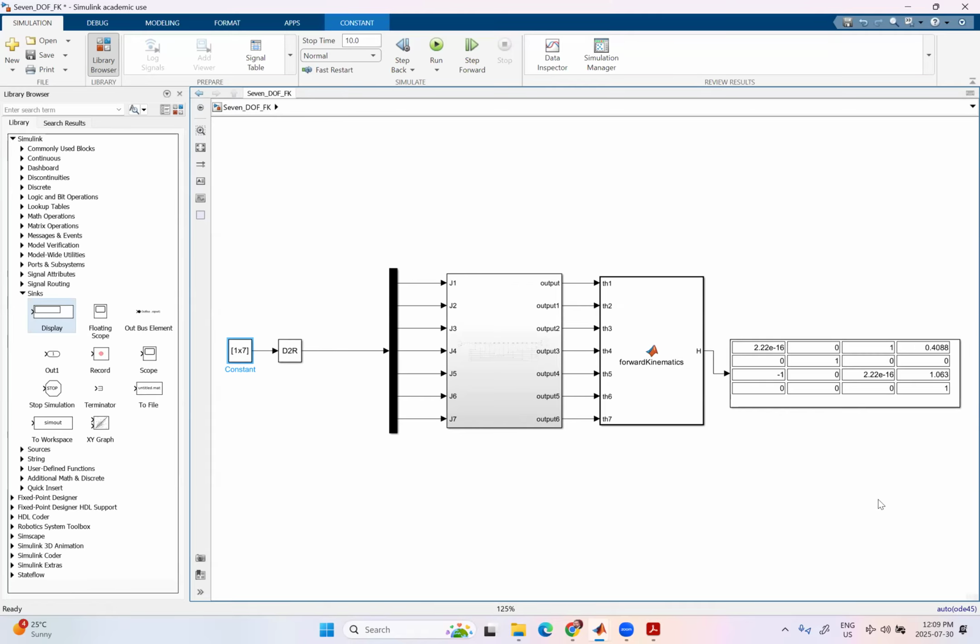And what are the next steps? Inverse kinematics, trajectory generation, and a control loop can be added. So as opposed to manually inputting values here, I need to generate angles or torques, or control actions basically, and then feed them to a controller, to my actuators, and make this robot move. Then we can observe its motion and feed the controller with the data we are reading off the encoders and so on and so forth.